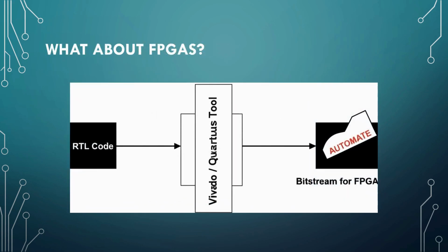And a very quick note to my FPGA developers. When you click on implement in Vivado or Intel software, you are performing the entire backend and construction process, for planning, placing, and routing, all automatically on a pre-built fabric of the FPGA. You are using the same principles on a reconfigurable skyscraper.